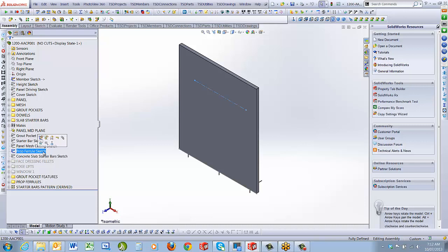Usually, rule of thumb, they're about 2/3 of the way up the concrete panel, so you can essentially just do a quick design. I'll set it up so that there's an equation for that, so that it's roughly around 2/3 up the panel from the base or from the support, because you may end up setting your panel down 400mm. You might want to calculate from the top of the slab, because that's where it's going to be fixed.